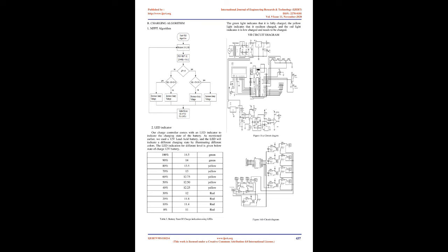4. Float charge, 4th stage, from T3 until the end. In this stage the control algorithm will apply to the battery a constant voltage V float, which is specified by the battery manufacturers. This voltage is applied to the battery with the objective of avoiding its auto-discharge.